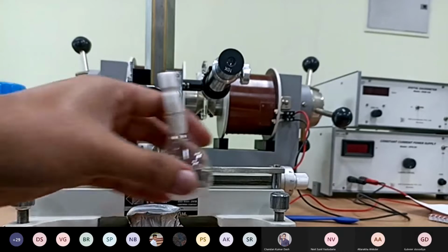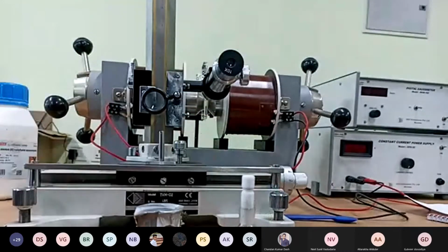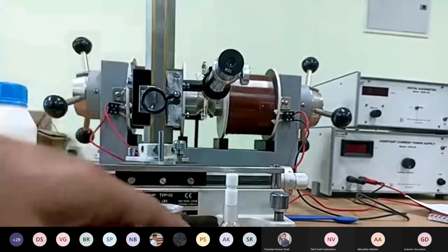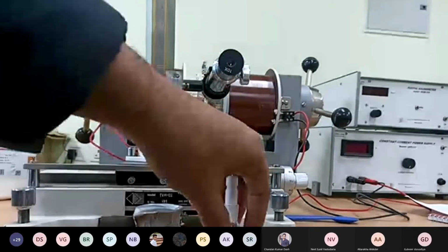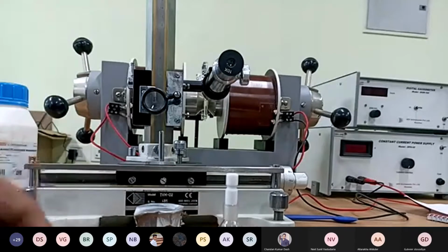So we'll measure the mass of the specific gravity tube. That will be called W1, and then we'll put the water and measure the mass again. The full volume we'll use, and that will be called W3, right?